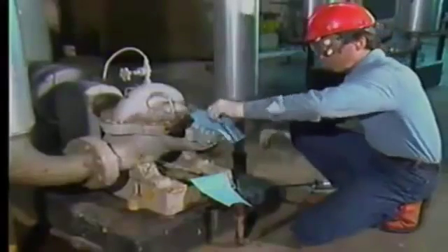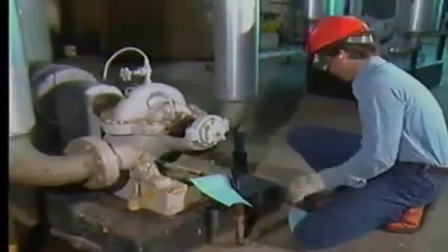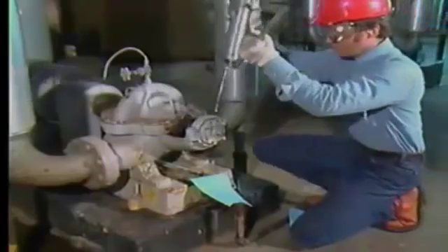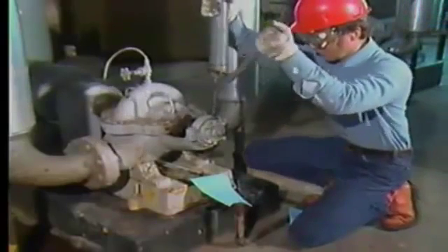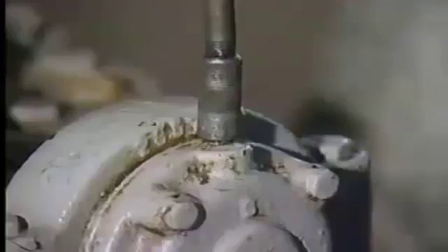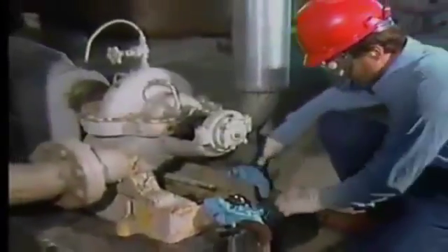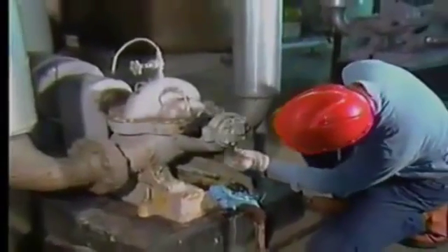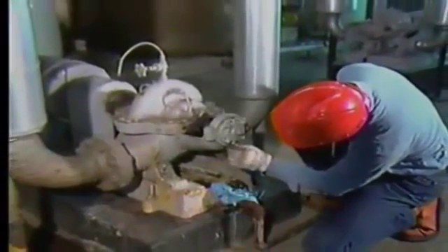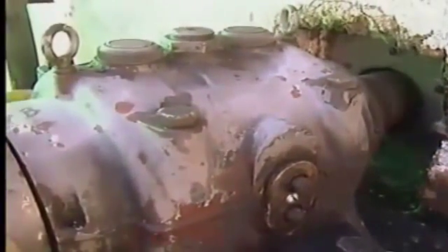Grease is occasionally used to lubricate some sliding surface bearings. When grease is used, it is generally pumped into the bearing with a grease gun. The grease is pumped through a grease fitting located on the housing. Check your plant's procedures to see how often bearings should be greased and how much grease to use. In any case, it is important to keep the lubricant free of contaminants and to make sure that the lubricant stays in the bearing.